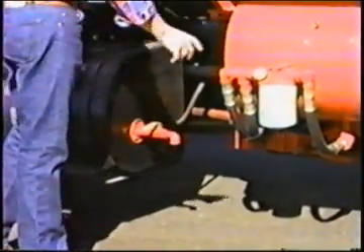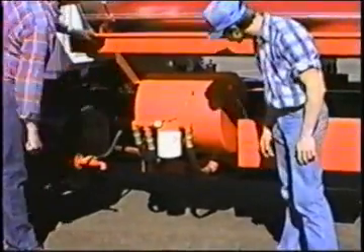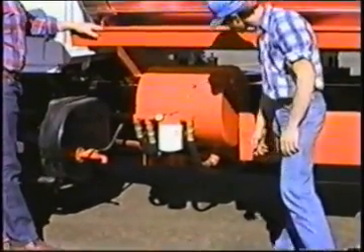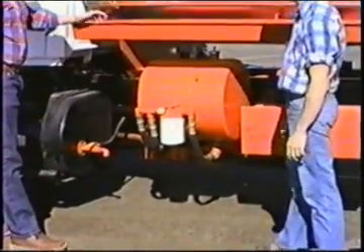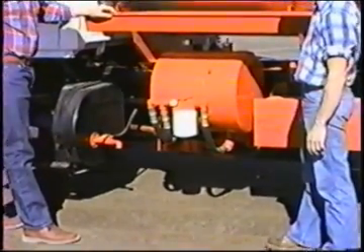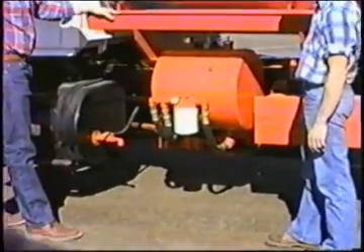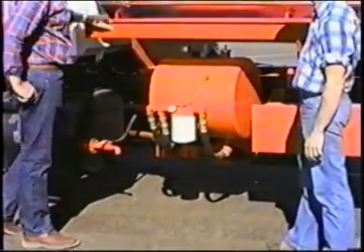Going on back here, this is a hydraulic tank. Got a sight gauge on it, and you should be able to see fluid in that when it's cool. When it warms up, it'll totally cover that sight glass. It's type F, automatic transmission fluid, Ford type. Pick it up at any gas station, buy it at about any grocery store these days.